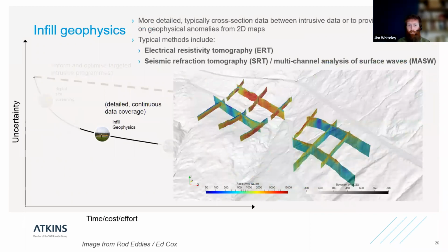Following on from that, I alluded earlier to the two-dimensional and three-dimensional techniques at our disposal. So these are the cross-section type data, the profiles, and I mentioned that normally these involve a modeling step. So there's a little bit more degree of understanding the data and having to really get to grips with what's going on, both in terms of your raw data from site, but also the modeling to produce the 2D tomograms. Generally speaking, the most popular method we have is electrical resistivity tomography. So again, resistivity, the inverse of conductivity I mentioned earlier. It can be incredibly useful to do a broad scale conductivity survey first, followed up by a resistivity survey, because you have data that can be related to each other in that case.